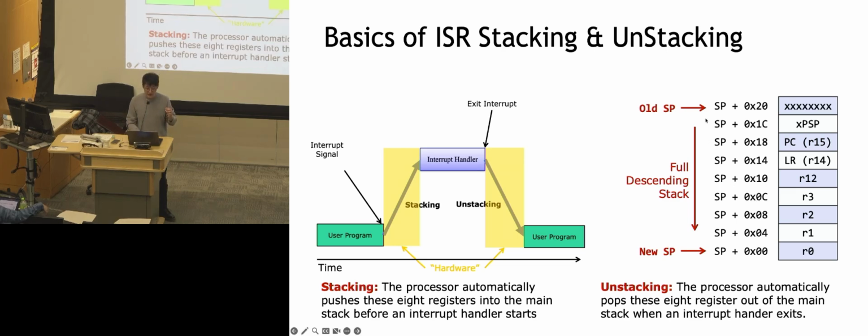On the right is a stack image. At the beginning, it will push down all those registers we mentioned, R0 to R3, then the link register, program counter, etc., and R12 because of intermediate calculation.